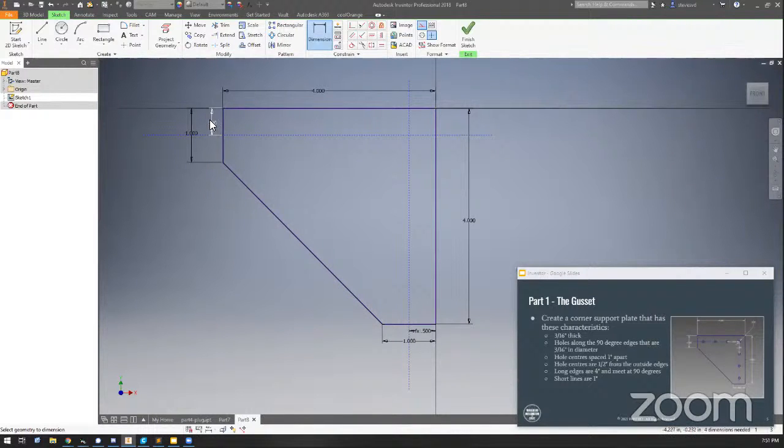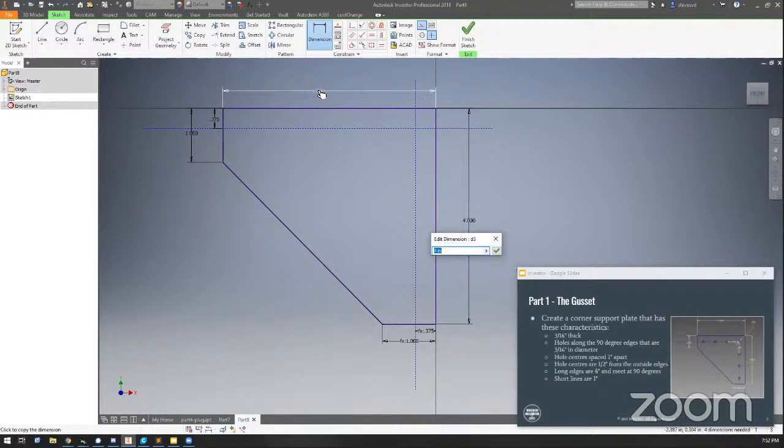So now if I go and alter this and say they don't want it 1/2 inch, they want it 0.375. It not only changes for this construction line, but it's altered this construction line as well, because this references this. So in this way, you can change the shape of these things with changing as few parts as possible. Knowing this, what we could actually do is in this one, assign it to this. And then with this one, assign it to this.